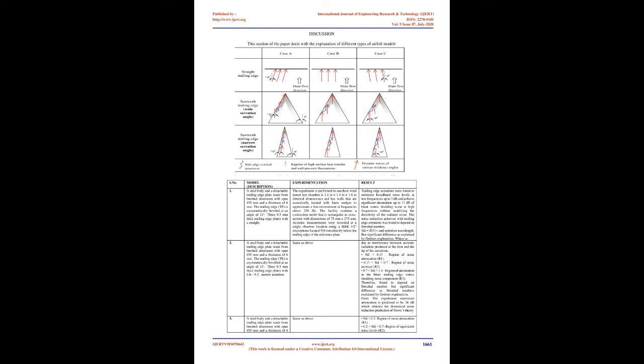The overall noise performance of the non-flat plate trailing edge serration type can be improved by the concept of Poroserrated trailing edges used in the current work. The bluntness-induced vortex-shedding tonal noise can be suppressed by filling the gaps between the adjacent members of the sawtooth by the use of porous metal, synthetic foams, or thin brush bundles.